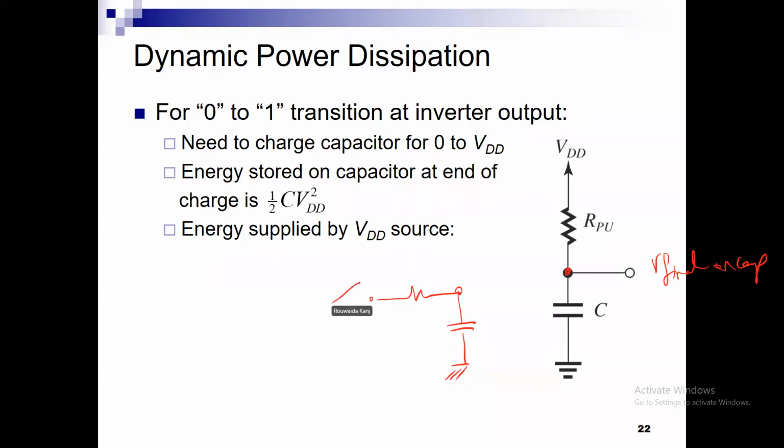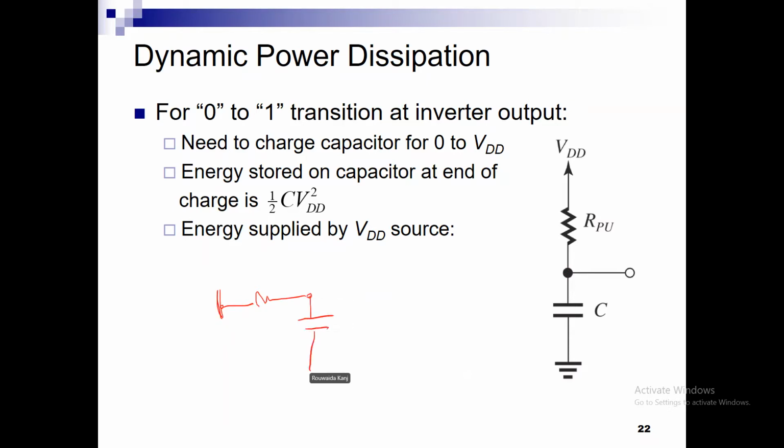Okay, this signal now, it's as if the NMOS turned off. Actually, let me clarify. The true circuit looks like this. I had a resistor that was always connected to VDD, and it was connected to the capacitor, and then I had the NMOS device with another resistor Ron that is connected to ground. Initially, my switch was on and this node was close to 0. We will assume that it was VOL.